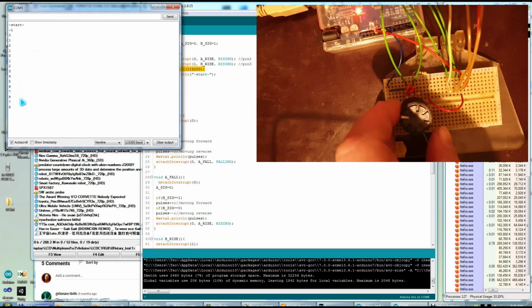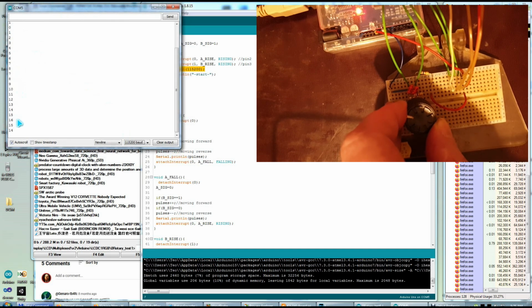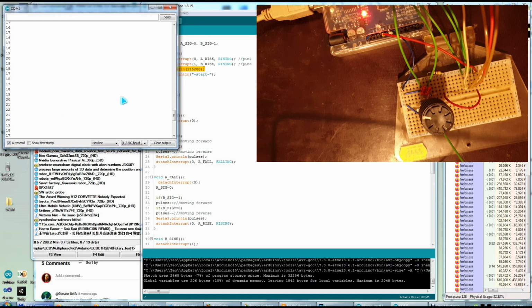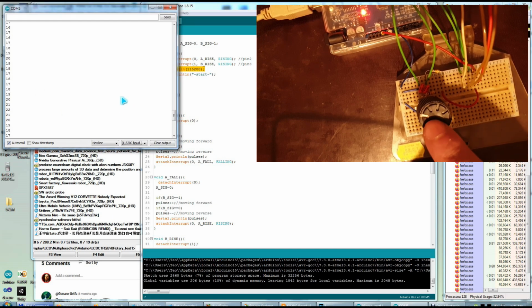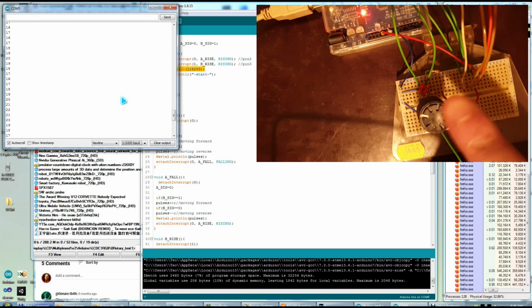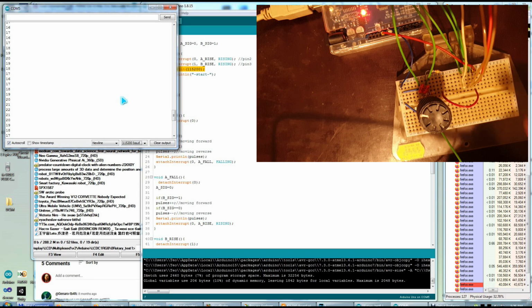But check this out. When I'm in the middle here, when I'm moving it between the holes, what garbage it's throwing. In my other tests, it did skip some numbers. Yeah, you see here, 17, 16, 17, 18, 19, something like this. There are a lot of errors in his code for this particular knob or rotary encoder that I'm using, and it is not the same as his. That's the point, although the circuit I'm using there is the same. The resistors are going to the positive and the common negative and everything. It's this bastard. It's that little bastard.